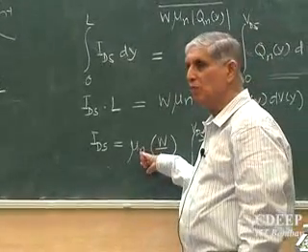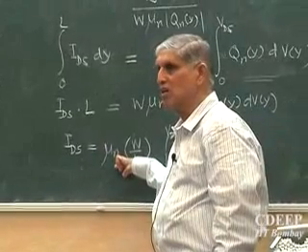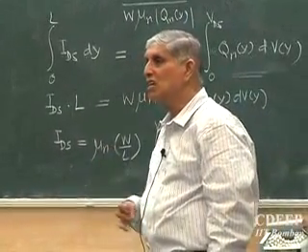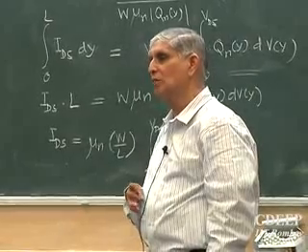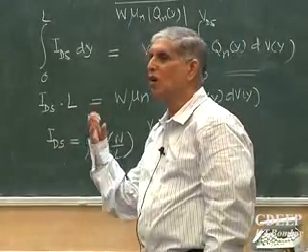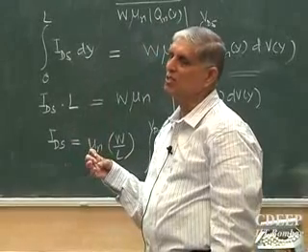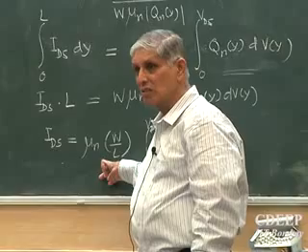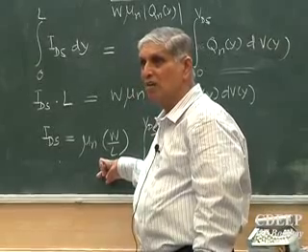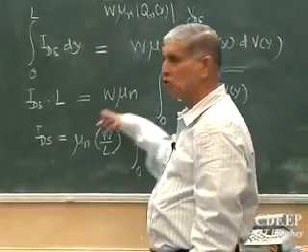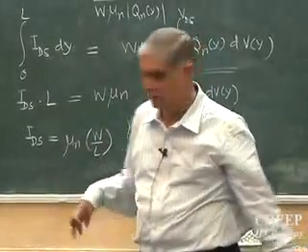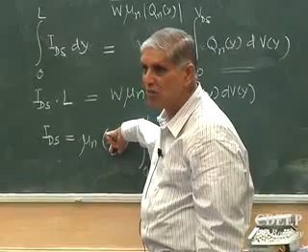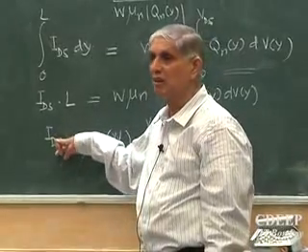As soon as you say mobility is lower or currents are lower for the same values, the current charging a capacitor will also charge or discharge it slowly. This means the speed of the circuit will reduce. So the advantage of power reduction is not so great. To increase that, what should I do? I should increase W by L. Yes, 2 minutes. I should use larger W by L transistors, so that what will happen? It will provide larger current.